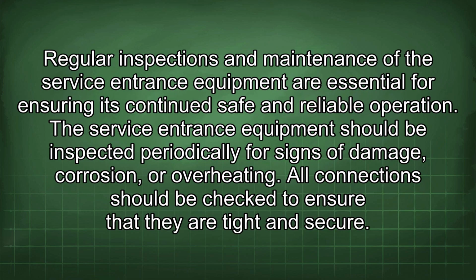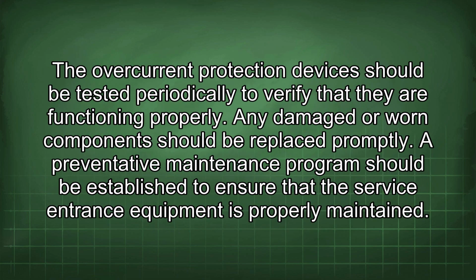Regular inspections and maintenance of the service entrance equipment are essential for ensuring its continued safe and reliable operation. The service entrance equipment should be inspected periodically for signs of damage, corrosion, or overheating. All connections should be checked to ensure that they are tight and secure. The overcurrent protection devices should be tested periodically to verify that they are functioning properly. Any damaged or worn components should be replaced promptly.